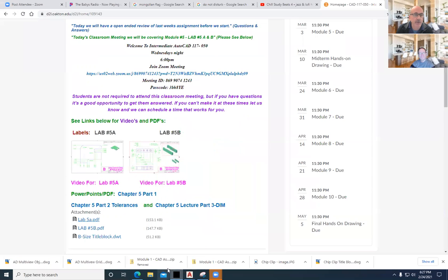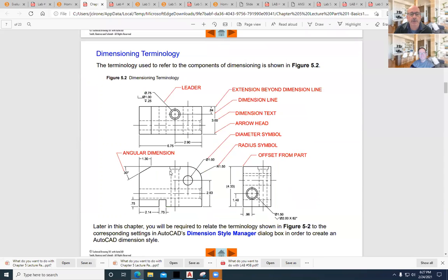All right. Returning, let's go back to where I was in my lecture. So we can pull these from the character maps, and you can copy and paste them into the text. As we work with some of our terminology, leaders are called multi-leaders. When we work with the CAD system, you can create a leader style.